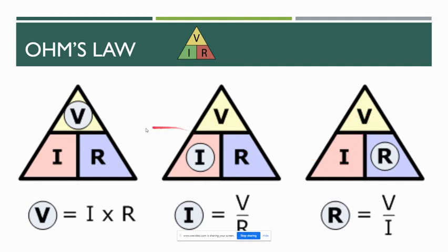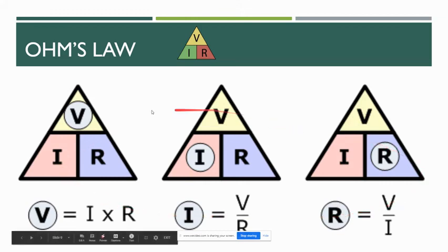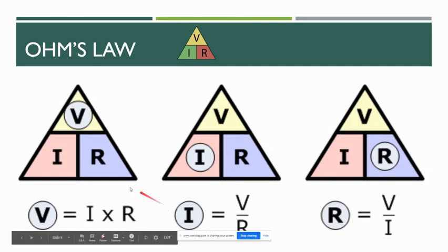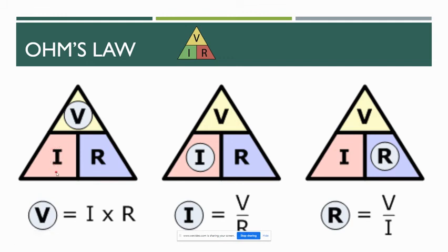The one thing to know when you use any of these formulas, though, is that when we use our numbers, we have to reduce or increase them to remove the metric modifiers. Metric modifiers are concepts like kilo or milli. So if I have 100 milliamps, I can't put the number 100 here.